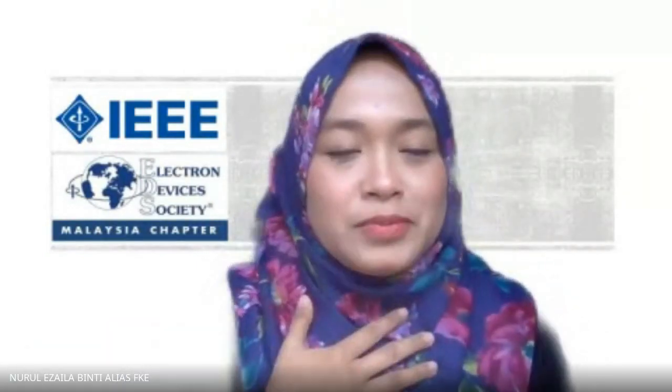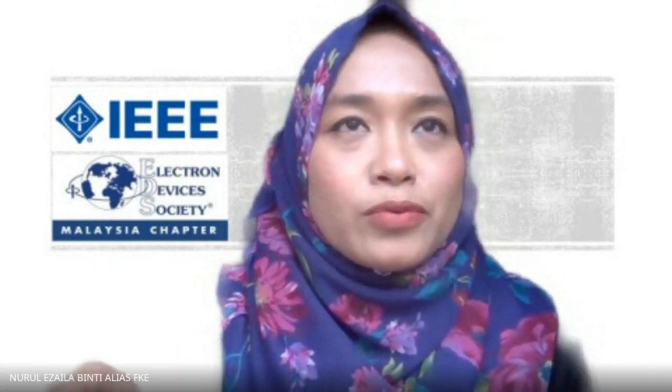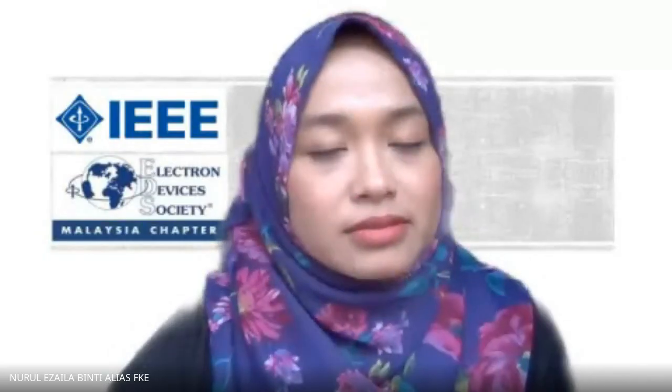Okay, Mr. Amri. I have a question for you. If I follow your presentation just now, the graphene-based FET you have also extended to the circuit simulation, right? Yeah. So how far has your team done on the circuit simulation? Is it the CMOS circuit? No. Actually, the circuit simulation is just to show that the extracted SPICE model is workable with a circuit simulator. There is a link between device model and circuit simulator, because to do the actual design with GFET, there are still a lot of things that need to be developed.